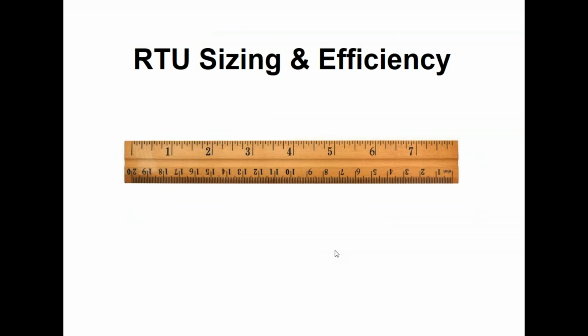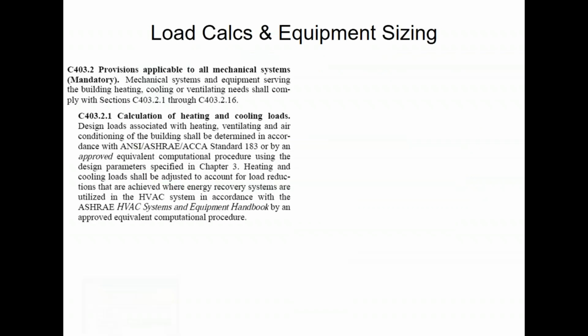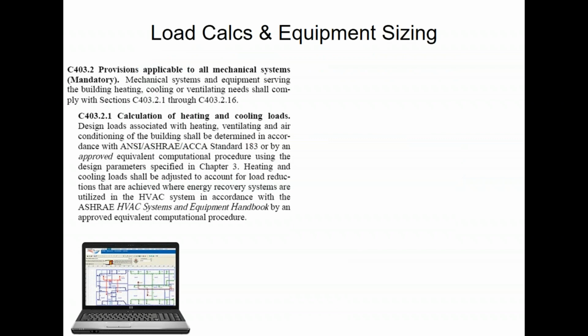All right, first thing in regards to rooftops, the sizing of the rooftop and the efficiency of the rooftop. Those are going to both come into play from a code mandatory standpoint. So on the sizing, just like other systems, packaged rooftop units are required to have a load calculation done per the energy code. The load calculation needs to be in accordance with the ASHRAE standard for load calcs. So that's pretty self-explanatory. At this point, if people do load calc, we'd be better off, let alone doing it correctly.